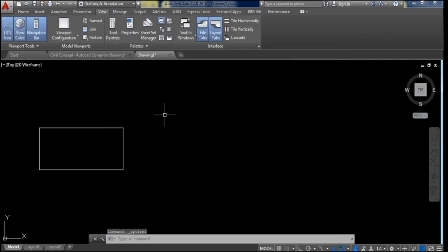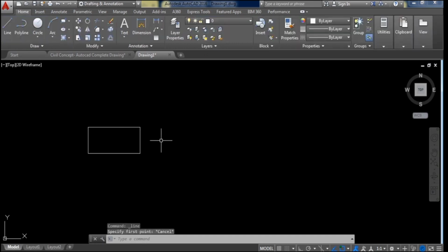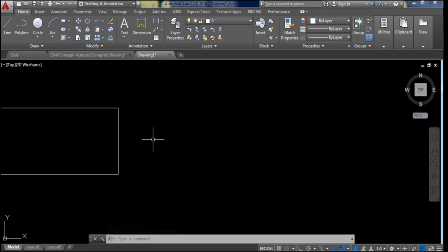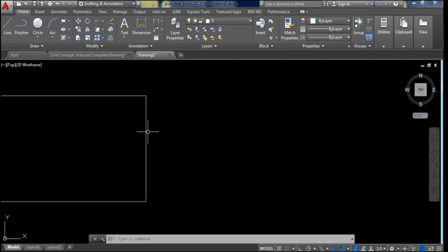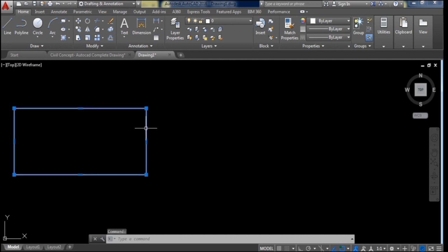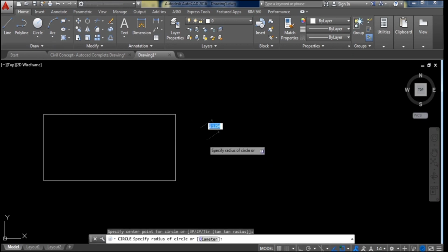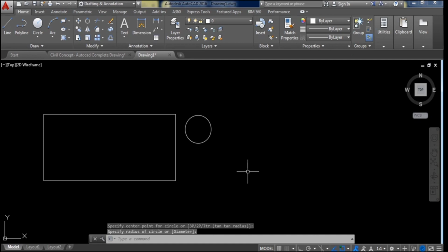It is important to set the appropriate size of the pick box, because for example, if we select an object in the workspace, then we have to move the pick box to touch the object so that we can select it. If the pick box is small, then it will be harder to select the object. If it is larger, then it will be harder to select one object when two objects are close to each other. So it should be suitable in size.